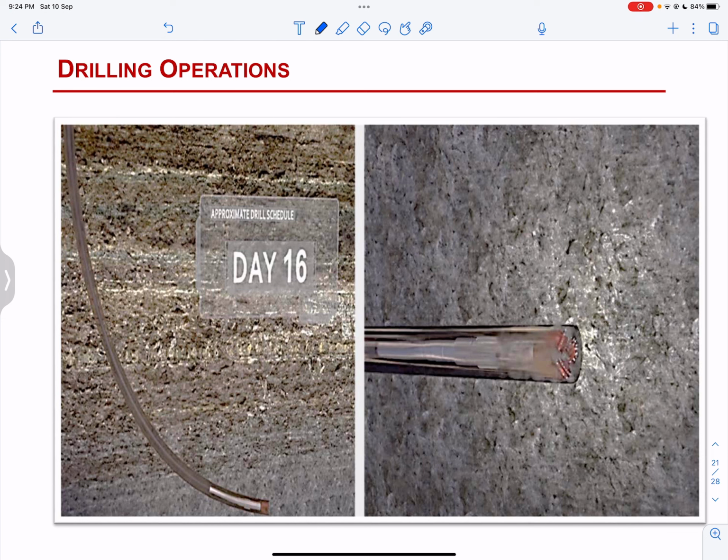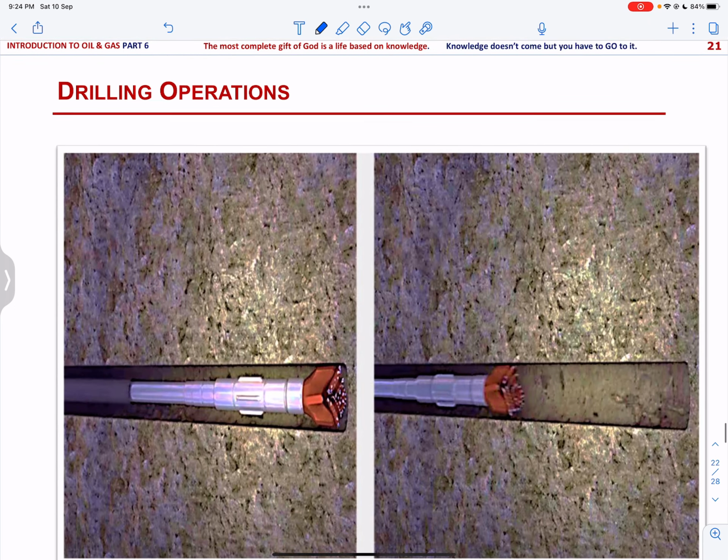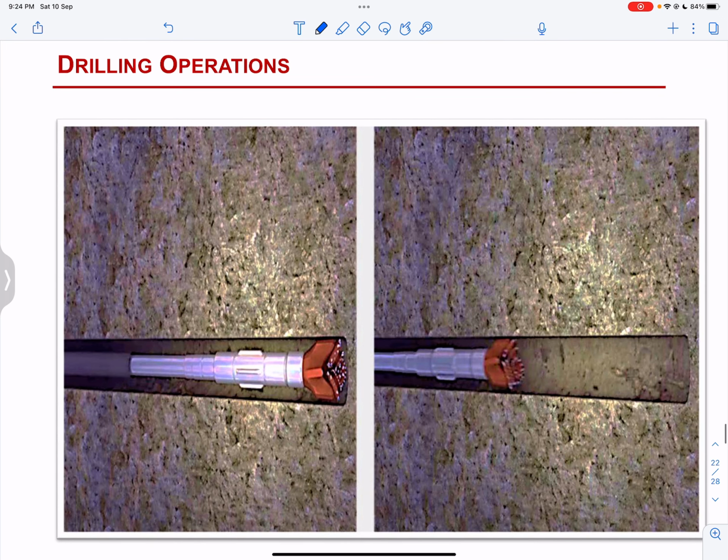The drilling method employed below the surface casing uses drilling mud, which is a non-hazardous mixture based on bentonite clay or synthetic thickeners. In addition to lifting the rock cuttings out of the hole, drilling mud also helps to stabilize the hole, cool the drill bit, and control the hole pressure.